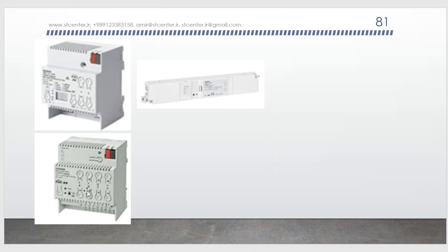We have the Dali Master and some sort of Dali Actuator Master. But an important thing, when you use it from KNX, for most of the time there is no need to use the Dali power supplies, because these Dali Masters are connected directly to the 230 volt from the utility, and can provide the right power supply to the Dali driver.